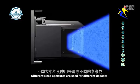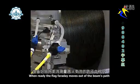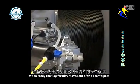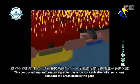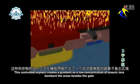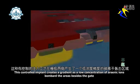Different sized apertures are used for different dopants. When ready, the flag Faraday moves out of the beam's path and allows the implant to occur. This controlled implant creates a gradient as a low concentration of arsenic ions bombard the areas beside the gate.